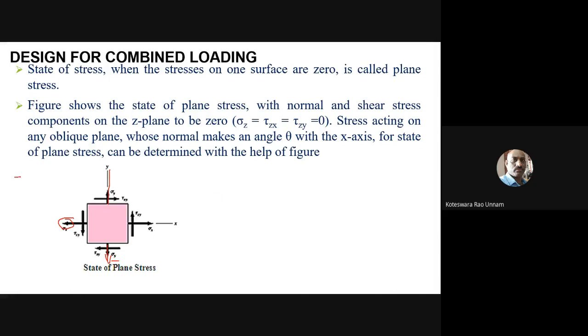Like I said, negative will become positive. Now, if I take this face, what is the outer normal direction? This is the outer normal direction, and it is in negative y. The stress is also acting in which direction? Negative y only. So both are negative. Negative into negative will become positive.